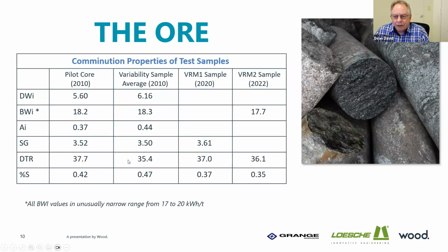That's around 35 to 37% magnetics, but that includes pyrrhotite, and that's not nice for the concentrate. So this percent sulfur number is important, because you have to get down to 0.05 before it's useful, or else you make sulfur dioxide in pelletizing, and you destroy the pelletizing plant.